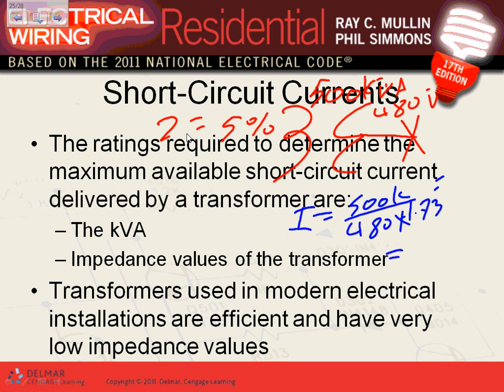Press, can you give me the answer for this, please? So 500 divided by, is it 600? It's 602. So the full load current is 602 amps. So basically, find the full load current of the transformer. That's easy, right? To find the short circuit, first find the full load current of the transformer. That's step number one, piece of cake. Step number two is, my friends,